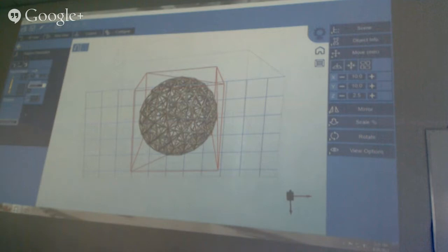This is one of those areas that is very hardware specific. Automatic support generation, generally similar to an FDM printer, figures out where you need support based upon the angle of the overhang. But for this printer in particular, angle of overhang is very crude, because DLP SLA printers like this can produce perfectly flat overhangs. I can have 2 posts and bridge 10 centimeters, no problem, with a roof that's a totally 90-degree overhang.